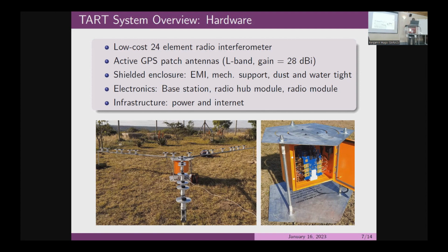Now the third part is that we were really excited and we went ahead with the installation, and we didn't characterize the site. As Jonas said, when you want to get a radio astronomy site, you must characterize it to ensure that it is radio quiet. When we were picking the site, we said, okay, down this side, there's more of the potential RFI because of all this stuff, so let's go up there where it's just 2 or 3 people living. But we didn't characterize the site. So we need to characterize the site.